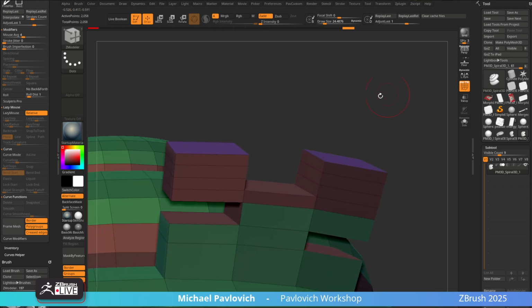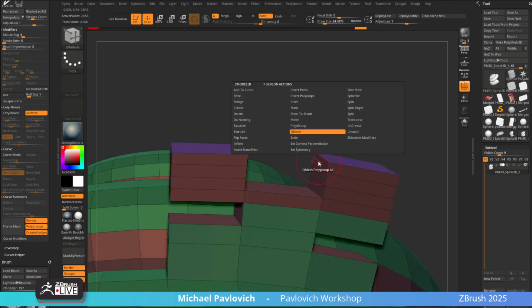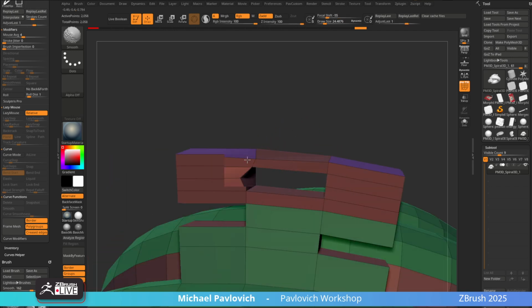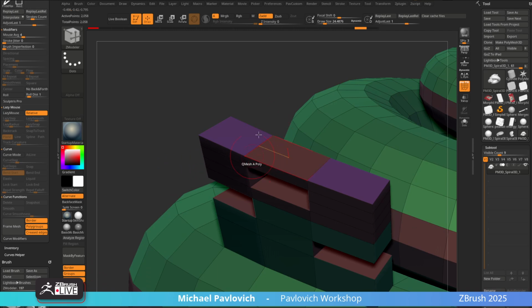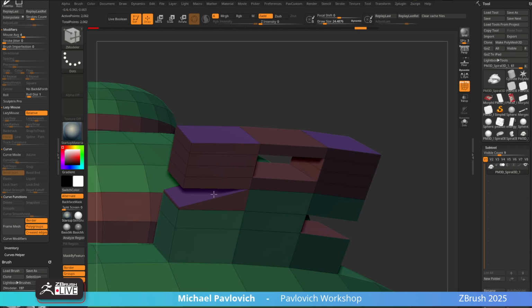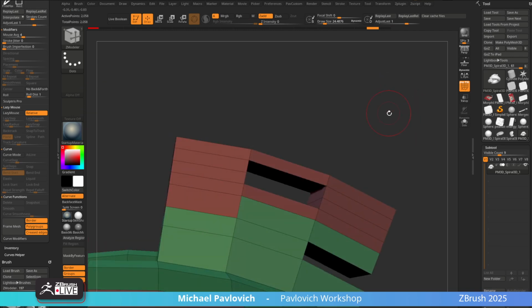However, it'll also bridge things too. So you can say start QMesh a single poly. As you start pulling over here, it'll want to snap to this, and now you don't have to bridge or merge or anything. It's just automatic. So you can go through here and pull this one up, and it'll snap here, and it's all welded together, right? If you like that functionality, great.